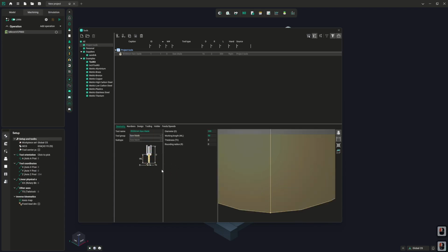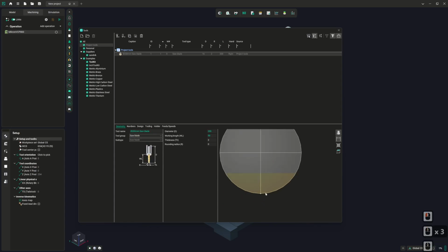We have saw blade definitions as well. Now, the thing that's worth noting in this instance is that the saw blade angle is typically in line with what the spindle would be as well. So it's assuming that you've got your saw blade mounted directly, as opposed to how it would be if, say, it were a very, very thin cutting disc in an arbor instead. Okay, so think circular saw, not slitting saw for this. If you need to define slitting saws, I tend to find myself using a standard cylindrical mill definition with a thin shank and a very wide mill tool.